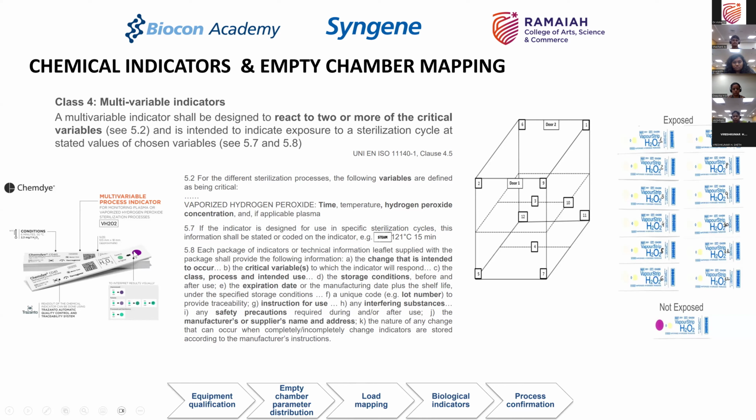And when these indicators turn from purple to yellow, or the indicators could have different colors, they could turn green, whatever color is defined by the chemical strip manufacturer. This here is a chem dye which turns green. This is another vapor strip, given by another vendor, which turns yellow. Then in such a situation you will be 100% sure that it is very clear. And this is just an example of how many are kept. You can keep any number in an empty chamber. So you will do this on an empty chamber and make sure that your distribution of H2O2 is right.